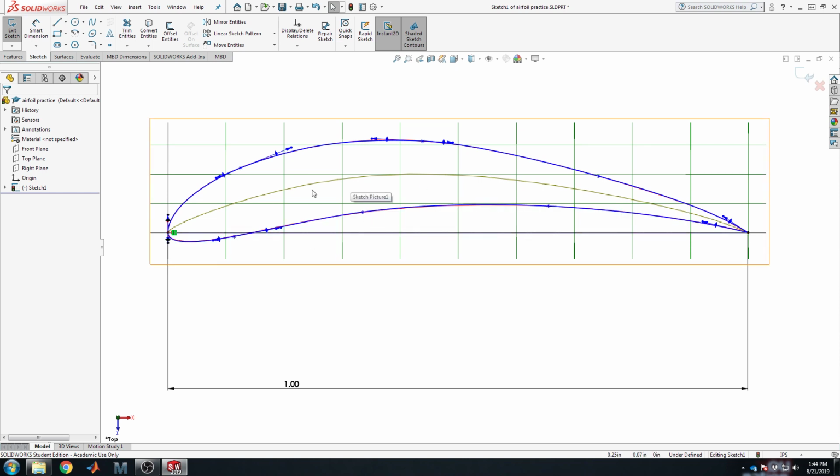So that's good. By having a top and bottom spline as well, you are creating a nodal connection in SolidWorks. This allows for the eventual surfacing panels to be divided at the leading and trailing edge, allowing you to easily manipulate, cut, and do geometric operations on the top surface or the bottom surface independently.